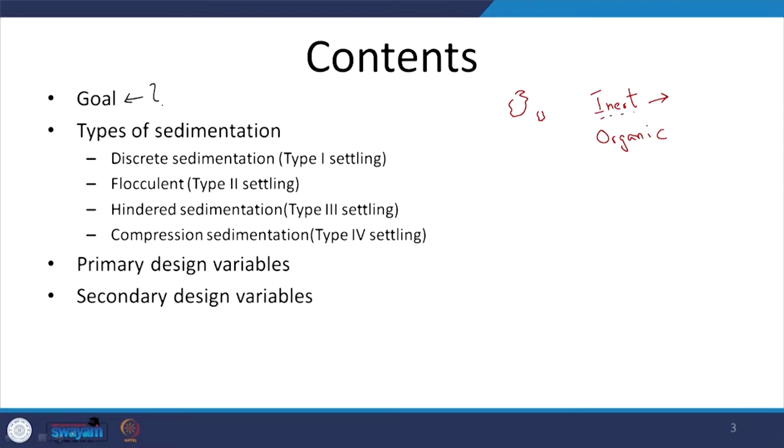So, that is when we already remove most of the bigger inert particles, but there will be some suspended inert particles which are relatively smaller than grit, and you will also have some organic content which is suspended. So, organic content, how do we remove typically? Typically, we will remove that by a biological process, where microbes in the presence of oxygen are going to catalyze this reaction of oxidation of your waste. Our waste is the microbes' food, right. Our waste is oxidized by oxygen, and the reaction is catalyzed, or the kinetics is improved, by the enzymes released by the microbes.